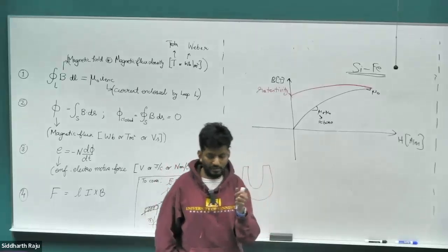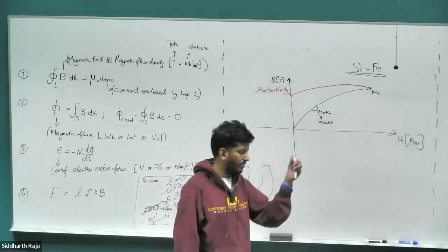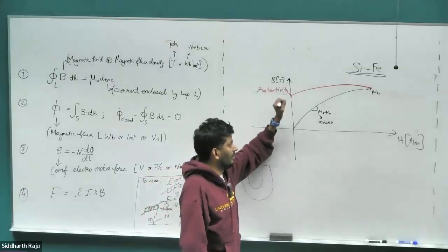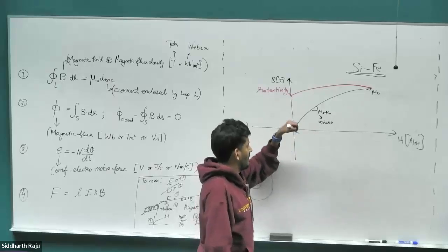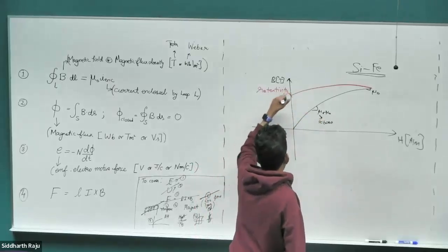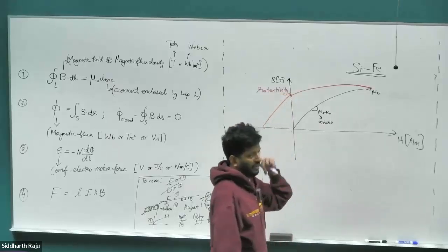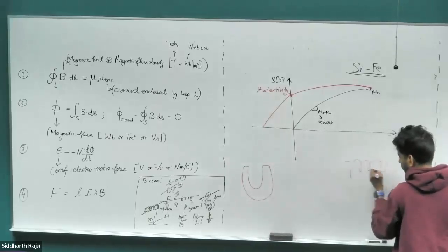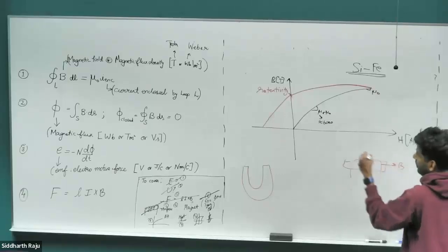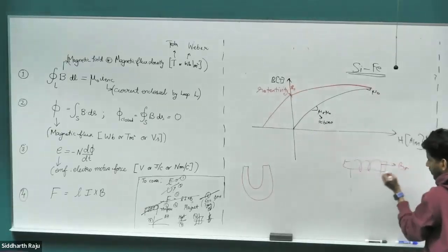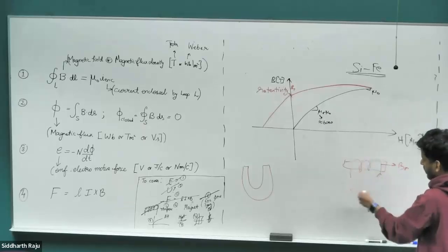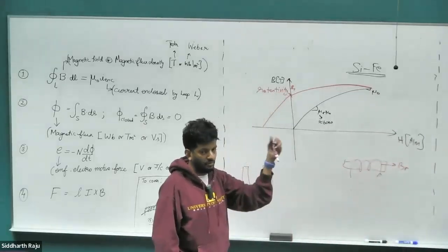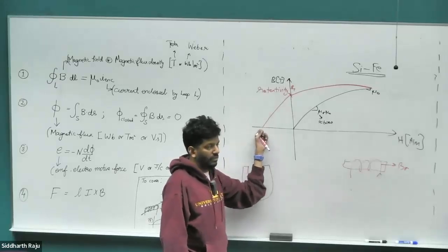When you have neodymium magnets, like those in your phones and laptops and all high-powered motors, those can retain the magnetic field for thousands or 10,000 years. The amount of time they retain it varies with material, but whatever remains is called the retentivity. To make this magnetic field go back to zero, you need to pass current in the opposite direction. The material you previously excited has created a magnetic field in this direction. Now to remove the retained magnetic field BR, you have to put current in your conductor in the opposite direction, negative current, so that the conductor creates a magnetic field in the opposite direction, which can knock the remaining aligned domains to a random state so that the magnetic field comes down to zero.